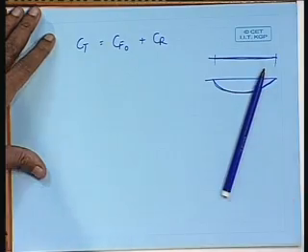In fact, I have drawn it in 2 dimensions. In 3 dimensions, when there is a vertical component also, the length that a water particle travels will be still more. Understood? Also, another thing will happen, as we have said before, because of the existence of a boundary layer, the pressure distribution will change as we go to the aft.